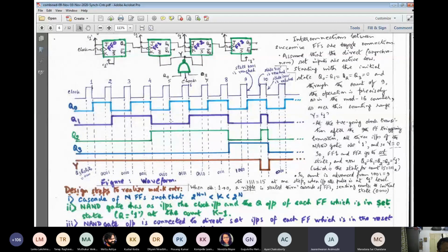So if I want my flip-flop to be Fs by 2, the Q0 output should be Fs by 2, but it should follow my clock signal, meaning it should be symmetrical with a duty cycle equal to the clock pulse. Is it possible then? Oh, that means you want to make the output of the flip-flops asymmetrical. Yes, sir. For Q2 and Q3, we can see that it is automatically asymmetrical. For Q0 it will always be symmetrical, 50% duty cycle. Here, however, it is not possible.